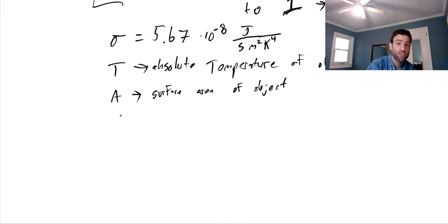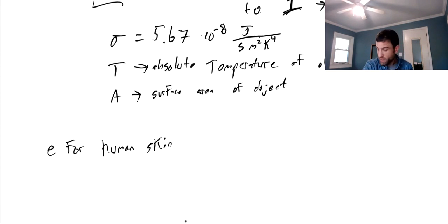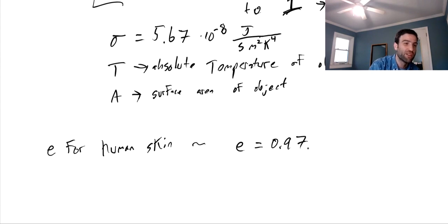different electromagnetic waves. So actually, the emissivity for human skin, even my skin underneath this shirt where I have a terrible farmer's tan, is still actually surprisingly high. You might have surprisingly close to 1, that is. Surprisingly close to as much of an ideal black body as it could possibly be. For human skin, even pretty light human skin, it's 0.97, right? That's great. The things, again, that have low emissivity tend to be things like shiny metals, right? Things like aluminum foil or gold or things like that.